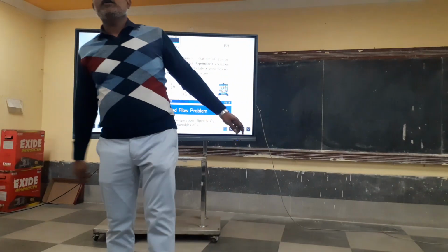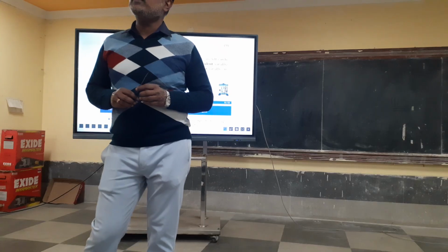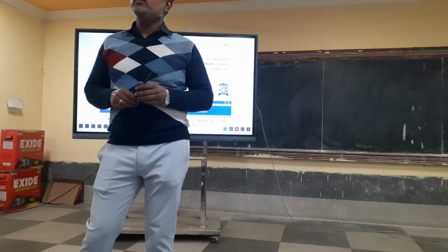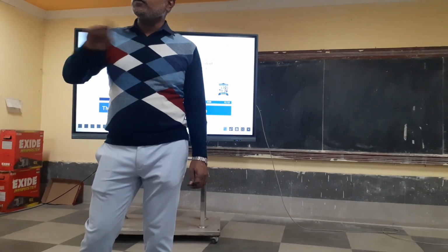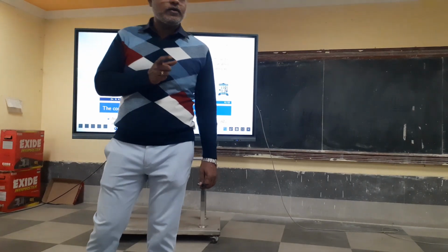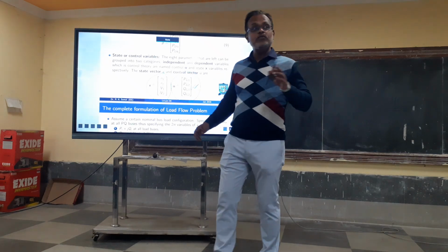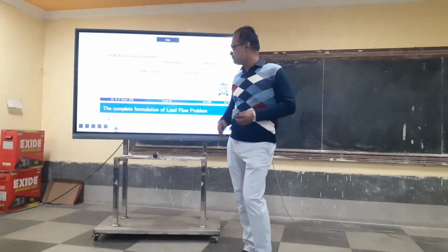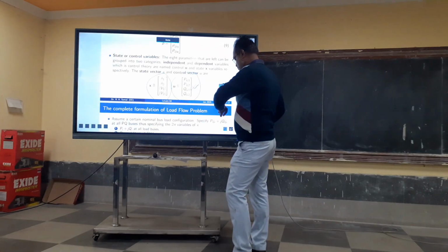PMU. Yes, very good. It is known as phasor measurement units, which measure the phase angles of the voltage. Because as we know, it is only the phase angles that dictate the power flow, not the voltage magnitudes. Phase angles are a system-wide phenomenon. Voltage magnitudes are local phenomena in a power system. Next.